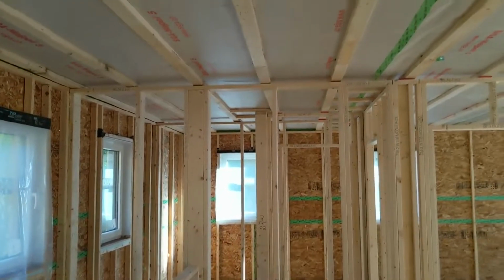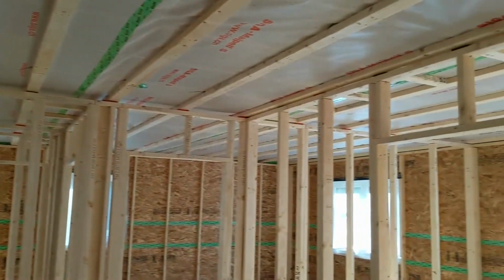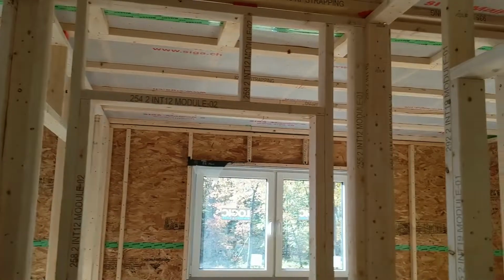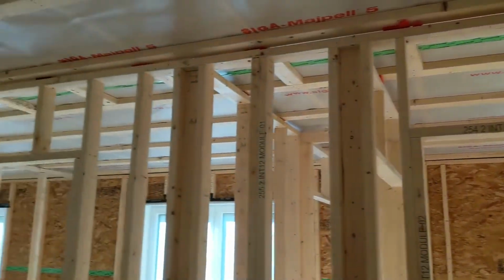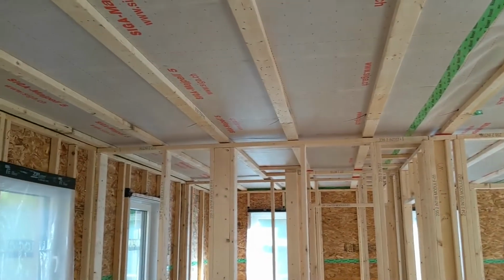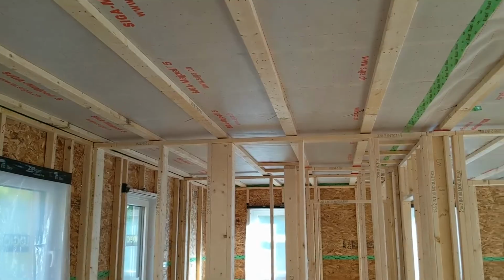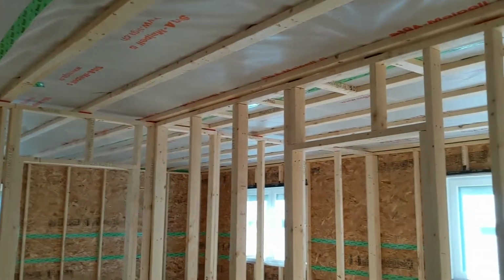It can be a little tricky with this membrane to get it airtight, but the guys do a careful job installing it, so I'm going to be checking that when the blower door is running. And then when the plumber makes his or her penetration through this membrane, we're going to have to make sure that that hole and any other holes are very well sealed, but that's really going to be the main focus of my discussion with the subcontractors later today here.